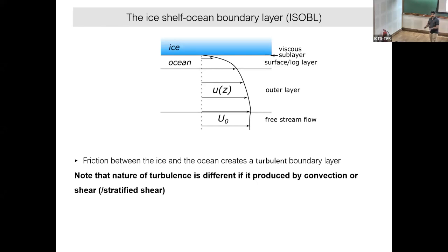So in an engineering problem, when there is a very high flow over a bottom layer, you start getting an asymptotic limit. The flow gets a self-similar pattern. In that self-similar pattern, you get three different layers. One is called the viscous layer, right at the boundary, because at the boundary the flow has to be zero, so from the boundary you get the viscous stress.